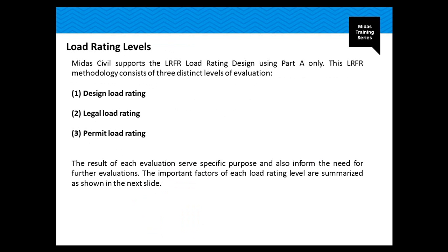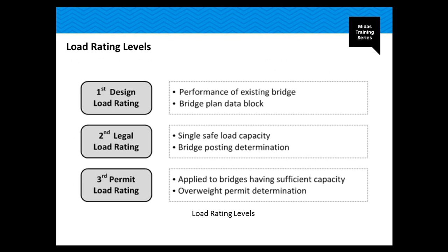Midas Civil supports the LRFR load rating using Part 8 only. And this LRFR methodology consists of 3 distinctive levels of evaluation: the design load rating, the legal load rating, and the permit load rating. We're gonna see what each one is for.